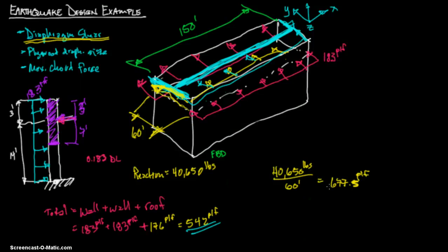minimum nominal panel thickness. That's not nearly large enough, so we go to 5/16, 3/8. Let's go all the way up to 15/32. So we go over 640, and then it has 730, and 730 is large enough, but 640 is not. And if we go down, 600 is 3/8. And so it looks like what we're going to need to use is a 15/32 thickness, and that's panel grade structural 1.